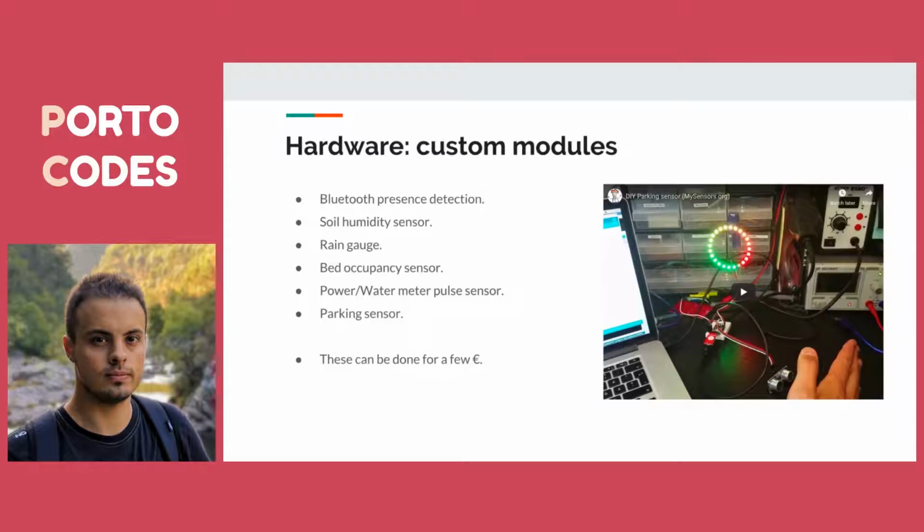The water meter also, probably some have, yeah. Like the magnetic thing. The new ones have a light, but the older water meters, the ones that have the, how do you say, the needle, have some magnetic thing there. You can place a Hall sensor that detects magnetic fields, and you can also count how much water you are using with that magnetic sensor. So yeah, those are fine things. I can't use them because my water and power meter are on the outside.